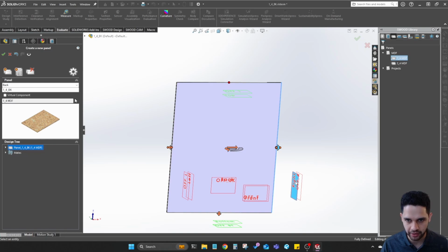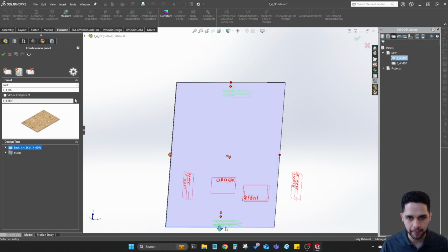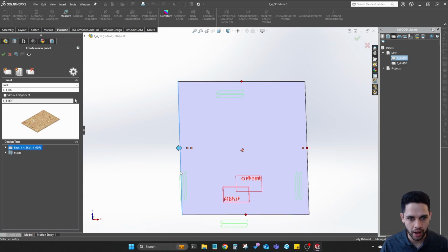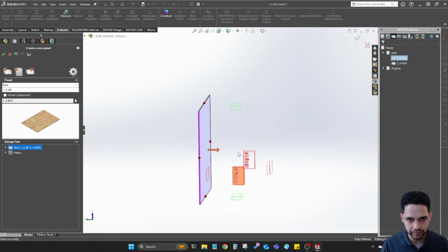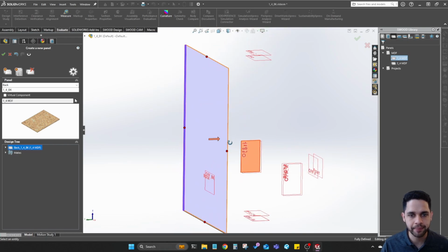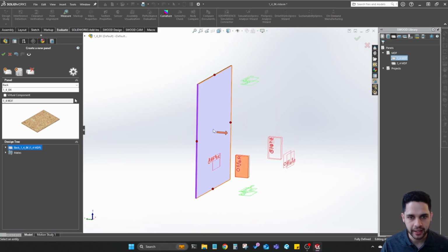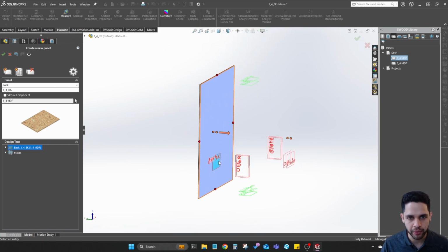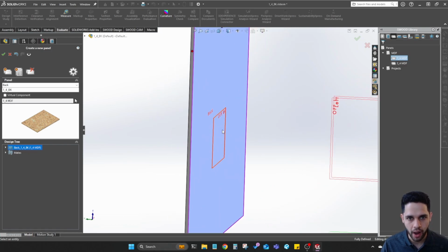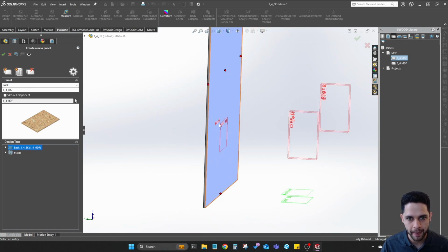So as you can see here, not the right, I want that offset right. I want not the bottom, but the offset bottom, and I want the offset left as opposed to just the left. And our last degree of freedom is going to be this offset back, and I'm going to measure that value from the front of this panel. So I want the front of the panel mated to that offset back.